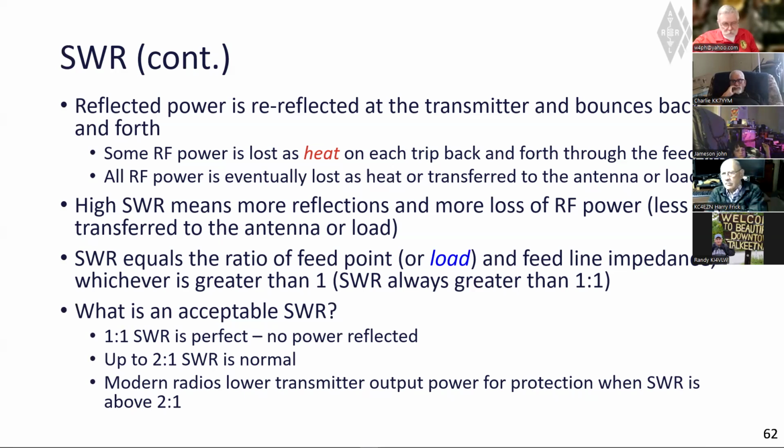As you go up a band, you go away from that frequency. As you go down a band, you go away from that frequency. So you're always usually looking at some SWR unless you're exactly on the frequency the antenna was cut and matched to, if that makes sense.